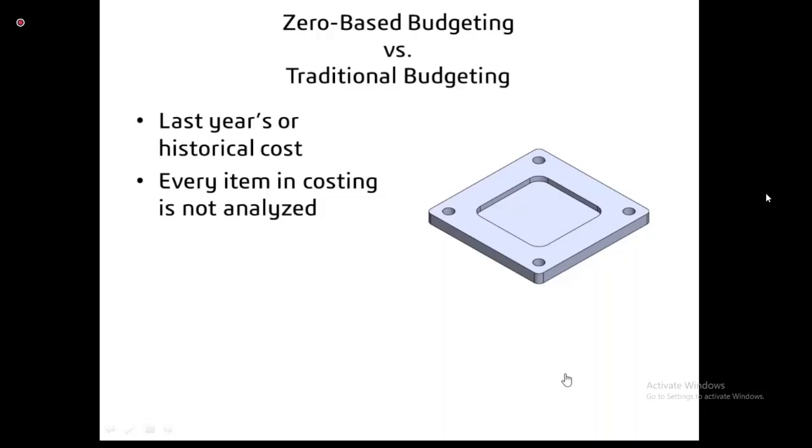When we reduced the cost from 950 to 730, we made a lot of changes in manufacturing. We made changes in the type of the tool. Whatever slab milling or milling operation was used on this component, we made changes in tool type, then in tool material, then in tool geometry, then in the manufacturing sequence of the component, then in the tool path. As it is a milling operation, there is a tool path generation, so we also optimized the tool path.